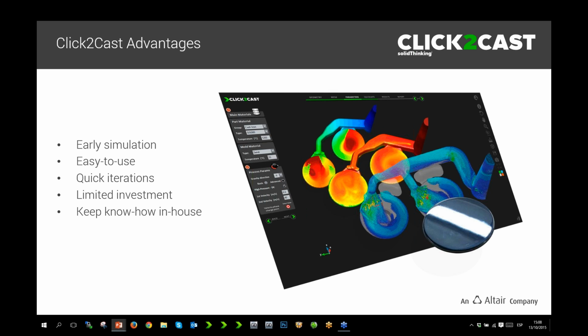Okay. What are the advantages of Click2Cast compared to other software in the market? First of all, and the most important, is that we can perform early simulation. What does this mean? This means that we don't need to define the whole process to start making simulation and to start understanding what is happening in our process. We can perform simulation just with the raw part, I mean with the designed component, without any running system, without any overflow, or without any air vents.